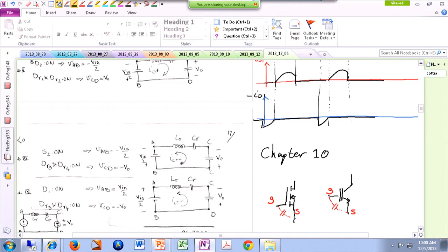Now, because you want your switching to happen very quickly, you have to charge and discharge this capacitor very quickly. By the way, the name of this cap is CGS, capacitor from gate to source. In terms of values, it's like several picofarad. I have to look at the data sheet, but it's either pico or nano. It's not like a microfarad.